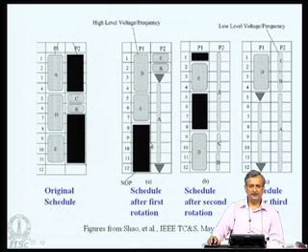But this example shows that loop rotation enables slowing down processors without increasing the amount of time. Okay. So, the time is the same, power consumption is less, so energy is saved. Okay. So, that is loop rotation and scheduling of the parts of the program, or rather parts of the loop, in order to save energy.